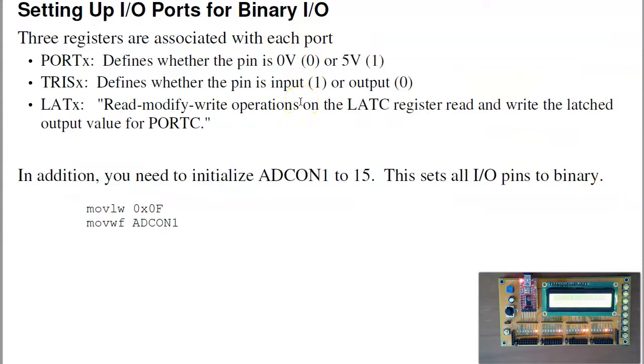To set up the ports for binary, you need to make ADCON1 equal to 15. We'll be talking about that a little bit later when we get to analog inputs. That'll be in a couple weeks.